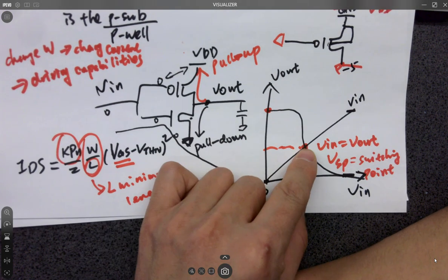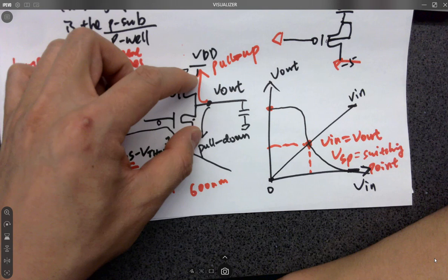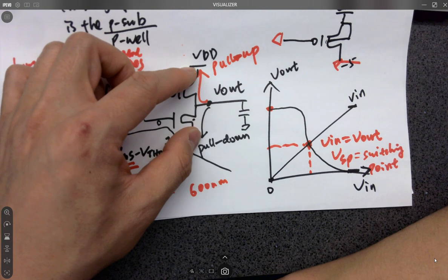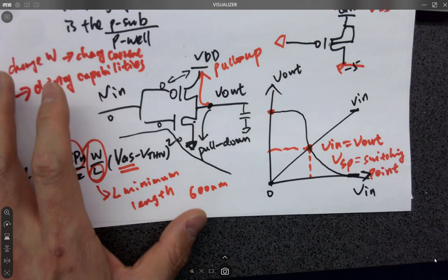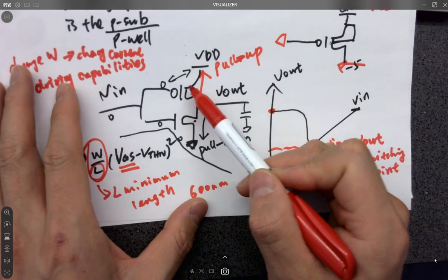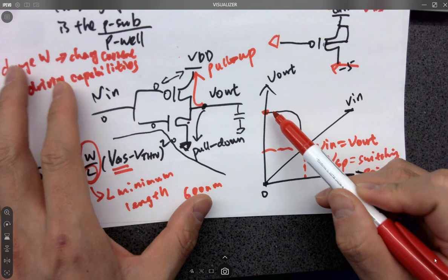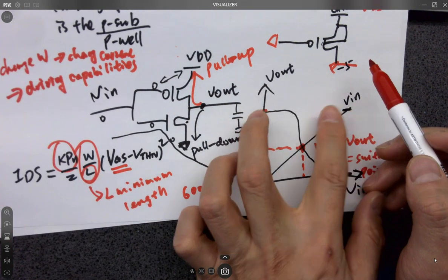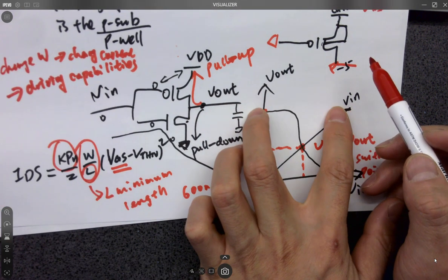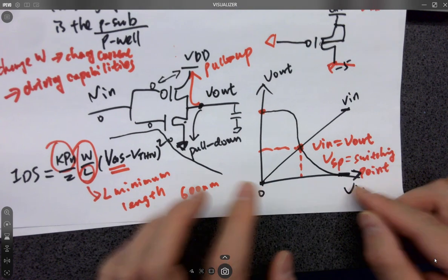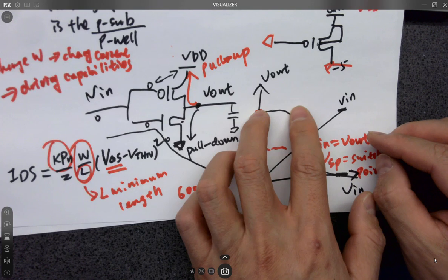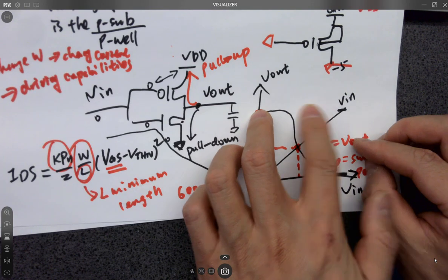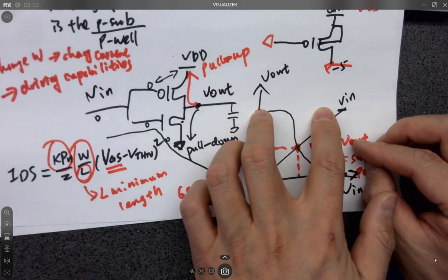But whenever it reaches the middle, both of us are pulling. So in that case, if you have a stronger PMOS on the top, it's going to hold the 1 for longer or shorter? It's not about time, but whenever Vin is changing, your PMOS is able to hold the 1 for longer if the PMOS is stronger.